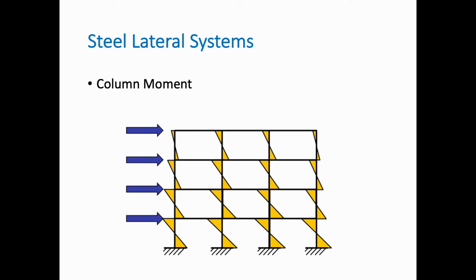And usually the point of contraflexure is at the middle of the column, where there is zero moment, and this is an assumption that we make because this is the ideal scenario. The not-so-ideal scenario is when we have a single curvature of the columns instead of a double curvature, where we will get much higher buckling. We do not want to reach that point indeed.